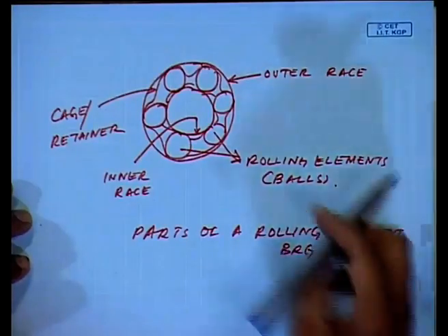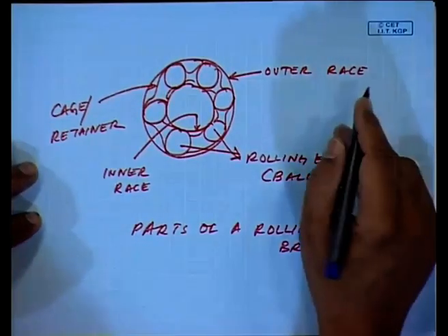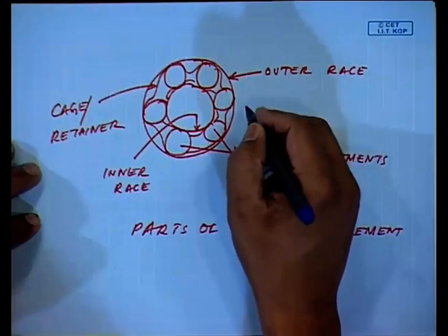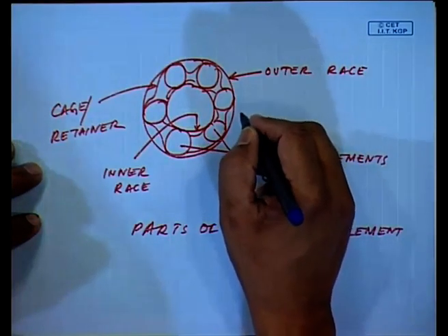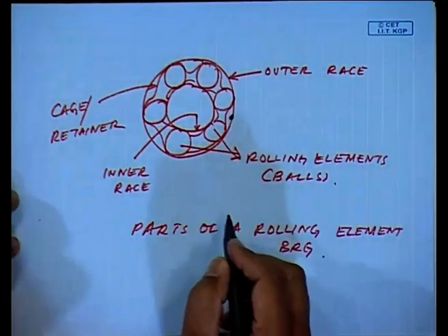So, in this case we had an artificial defect, okay, because we have a bearing manufacturer next door in Kharagpur. So, they helped us do these experiments. In fact, we could see the fault in these bearings. In one case we had a defect in the outer race where we had a pitting mark.